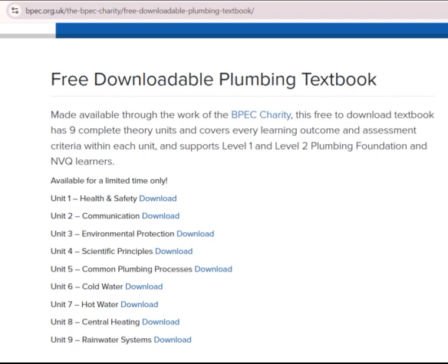The types of information noted should be the name of the maintenance engineer, the date and time the maintenance/repairs were carried out, the type of system being maintained, the type, model and make of boiler installed, the number and position of heat emitters installed, the date of the last boiler service, any faults with the boiler recorded, the type of maintenance/repairs undertaken, their location, the materials/components or replacement parts used.